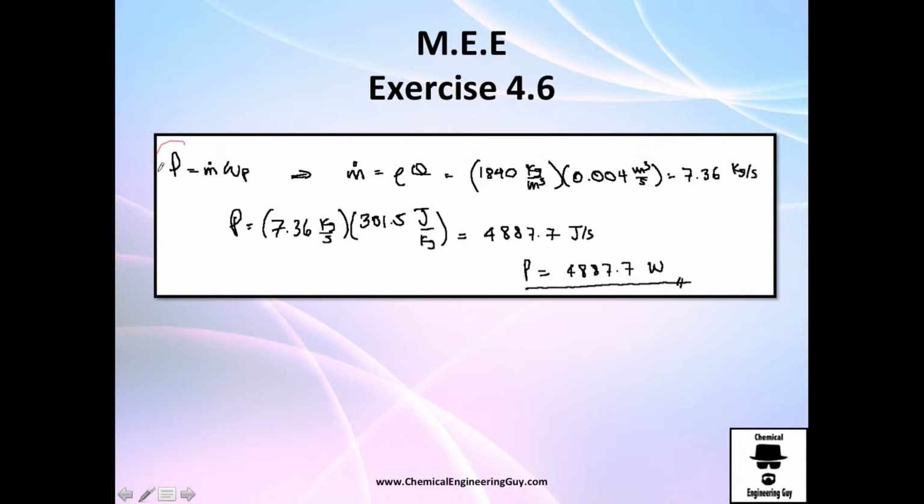But remember, power equals mass flow times the head of the system or the pump requirement. But we don't have mass flow. But if you remember, mass flow is essentially just volumetric flow rate times density. The density, do we have it?